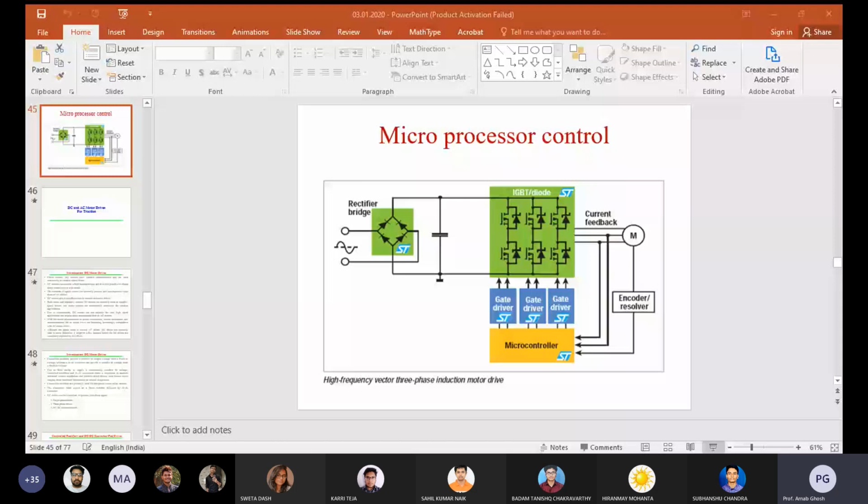Here we can see the different types of DC and AC motors for traction. In the case of direct current motors, different characteristics are there. The first feature is based on your input and output, that is, the availability of your source and what type of load you need to overcome. If the available source is DC and you have to overcome a high starting torque, then definitely the preferable motor should be the DC series motor.